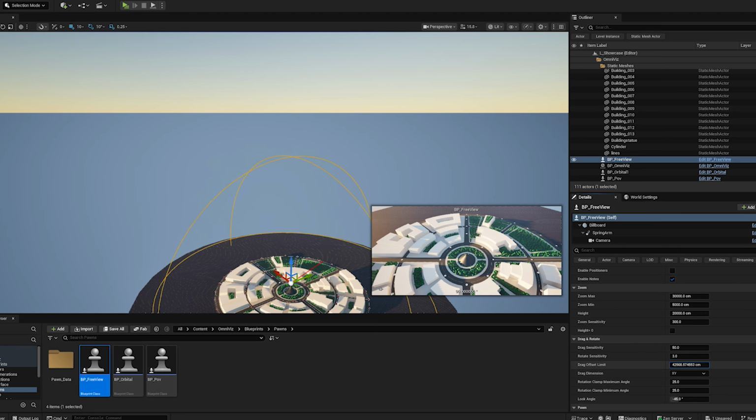First off, these measurements have to appear as UI elements, not 3D objects in the world. 3D text puts unnecessary pressure on the hardware. Plus, if an object gets in the way, your measurement is blocked. And since you never know the scale of a project, a 3D measurement might be too tiny to read from a distance. So, we use UI elements driven by enumerations to switch behaviors based on the measurement mode.